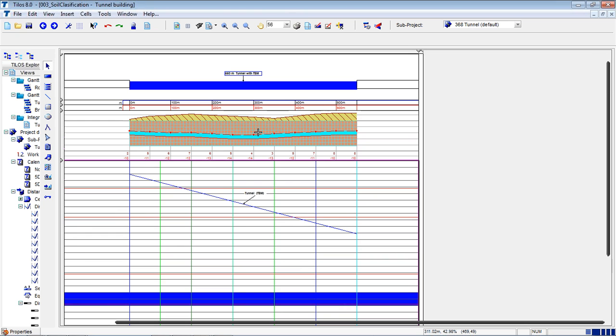Based on this TBM, because TBM works generally, I have planned more than 10 metro projects. Let me tell you my method of planning metro projects. Generally, I start planning a metro project with the TBM works, the tunneling works, because these are the critical works. After I set up the proper tunnel construction plan, I make the station planning backwards, because there is one important criterion. When the TBM arrives at the station point, excavation of the bottom floor of the station must be completed.